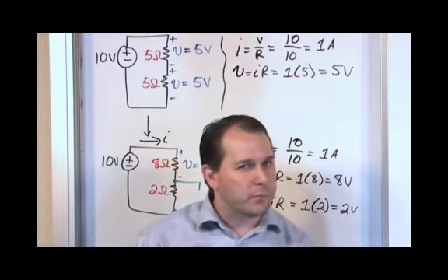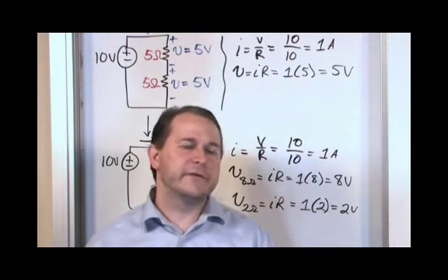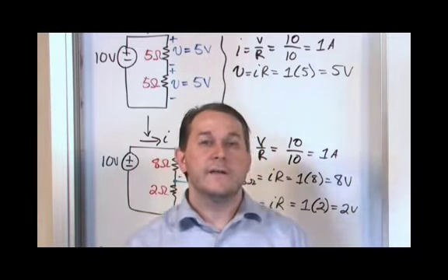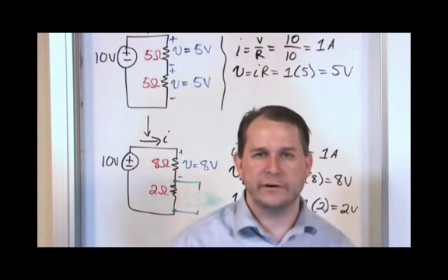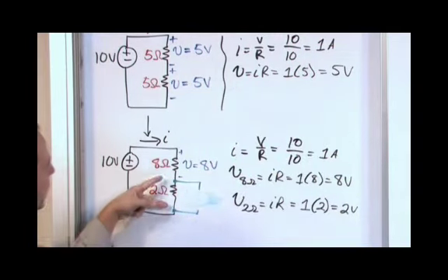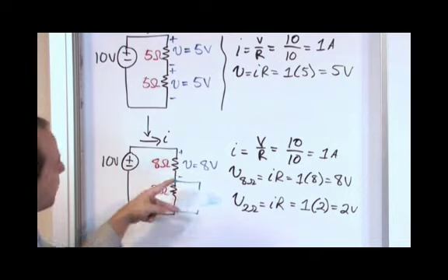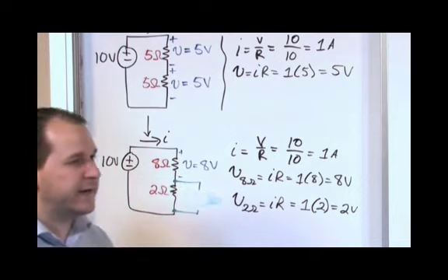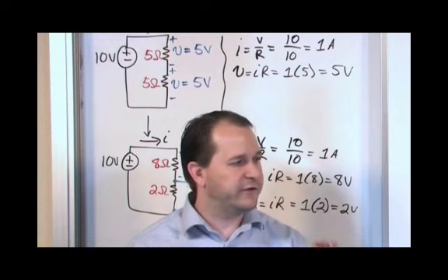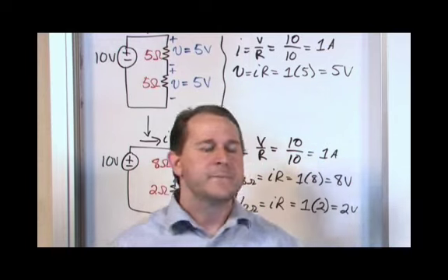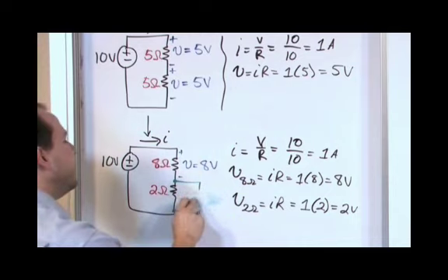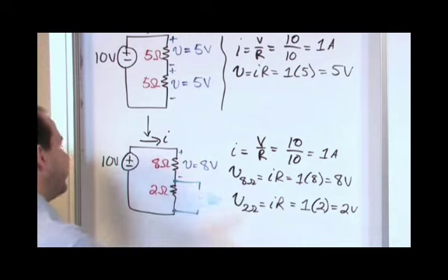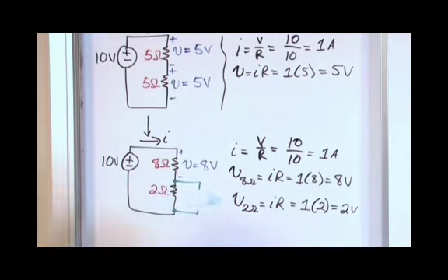Let me say that one more time. A lot of times in circuits, when you're talking about voltage dividers, they'll ask you to calculate the no-load voltage. When they say that, they mean they want you to calculate the voltage across the terminals that we're interested in, but with no load connected there. That's a perfect 2 volts delivered there. Now, if I connect a load, depending on the resistance value of my load, I'm going to actually change the circuit, and I'm not going to have really 2 volts delivered across that guy again, because I'm changing the resistor network.